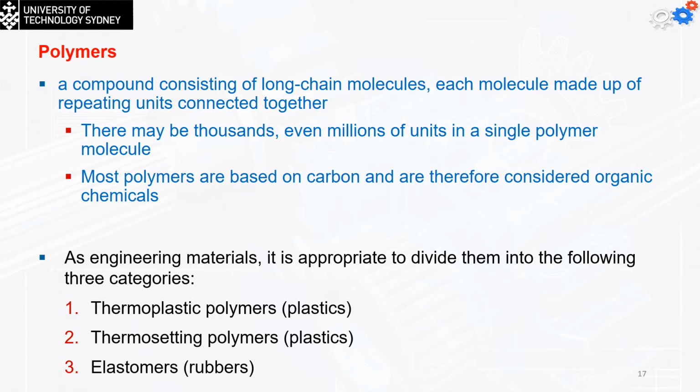On the other side, if I have epoxy, for example, two epoxy components mixed together, or even glue, I can put it on the surface, leave it to solidify, and add heat to accelerate this process, and at the end it is going to be solidified. Once it is solidified, I cannot remelt it and use it again. So that's what we call thermosetting polymers.